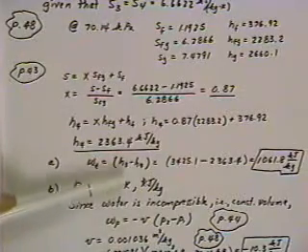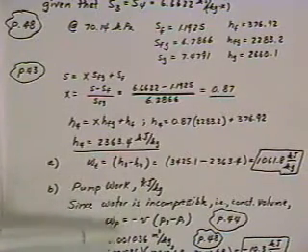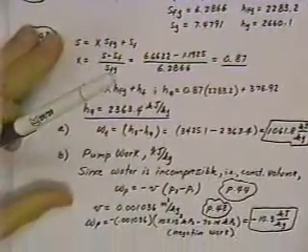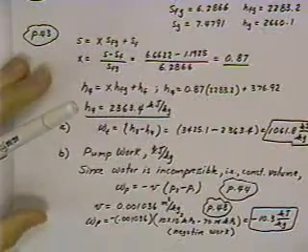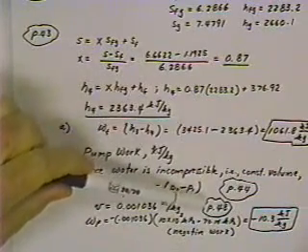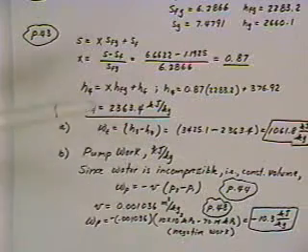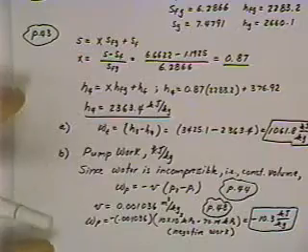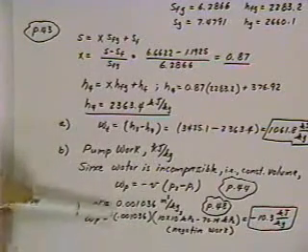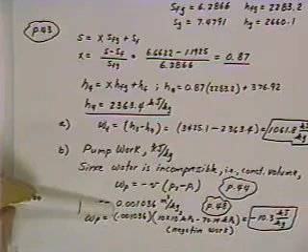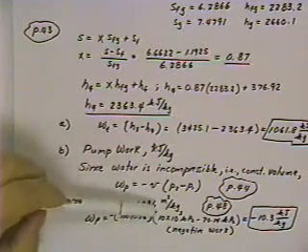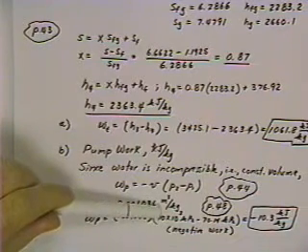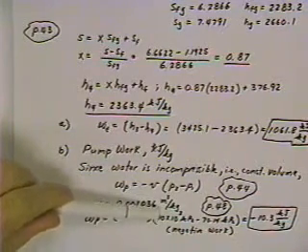So we look at the specific volume of water, 0.001036 cubic meters per kilogram, found from the tables on page 48 at the pressure of 70.14 kilopascals, V sub F. And so the pump work is minus V, which is 0.001036, times delta P. And we're pumping it from 70 kilopascals up to 10 megapascals.